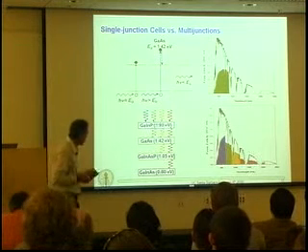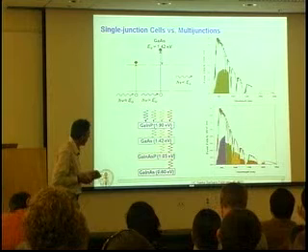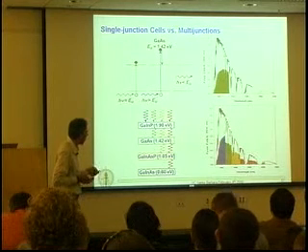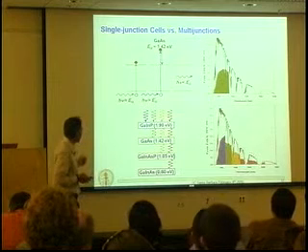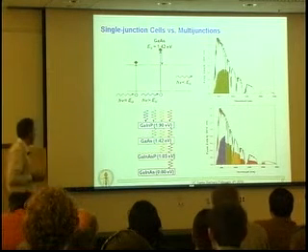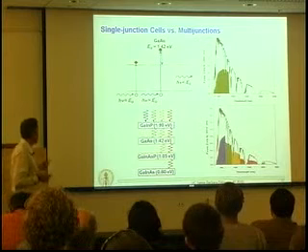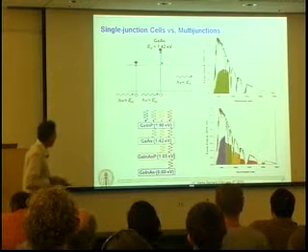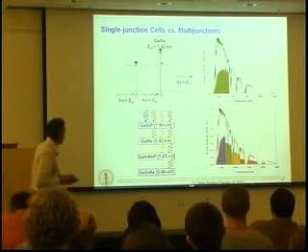So in multi-junction solar cells, we have this opportunity to both cover more of the solar spectrum and harvest a greater fraction of the power in the solar spectrum because of the smaller quantum defect per absorber layer that exists between the photon energy that's absorbed in that layer and the bandgap energy. And that's responsible for this big efficiency increase.